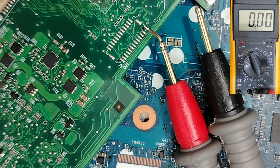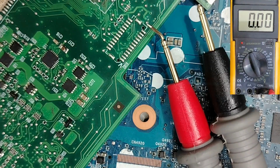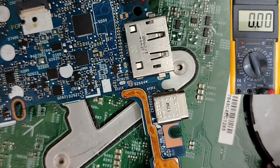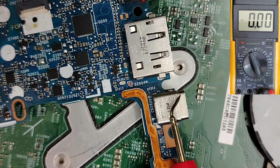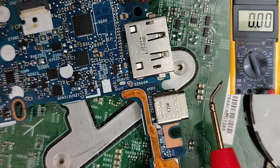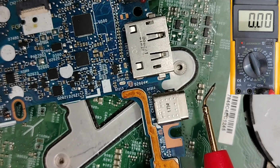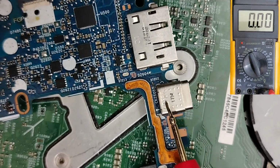I'm going to teach you the most common fault on a dead motherboard step by step. So let's get started. We're going to begin with the first cause of a dead motherboard. Of course, we're going to see some live testing using the multimeter, and we're going to go through many motherboards in order to understand everything. So the first common fault is the power jack.